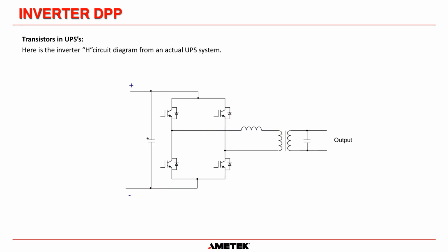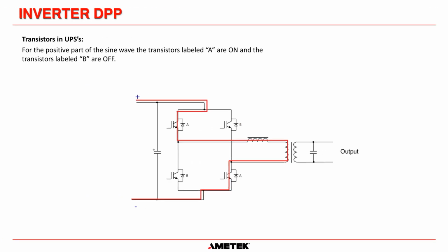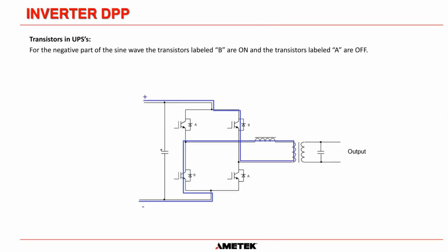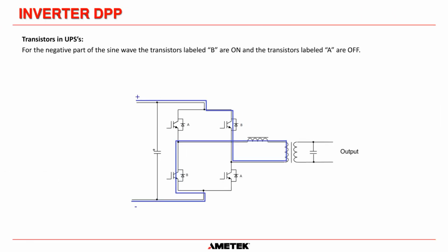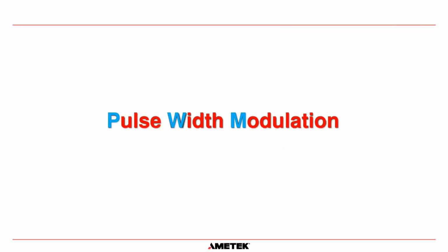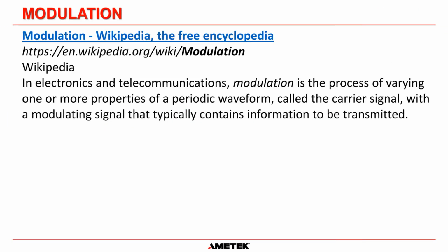But we don't use a square wave in the PWM system because we use the benefits of the high switching frequency of these IGBTs. And what we actually do is we switch the pairs on. We've labeled them here as A, and these ones here as B, exactly the same. We switch it on at 8 kilohertz using pulse width modulation, PWM, okay?